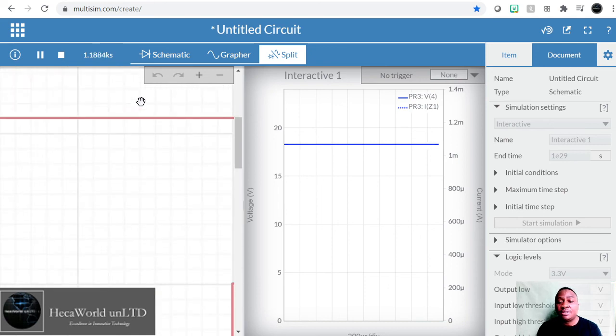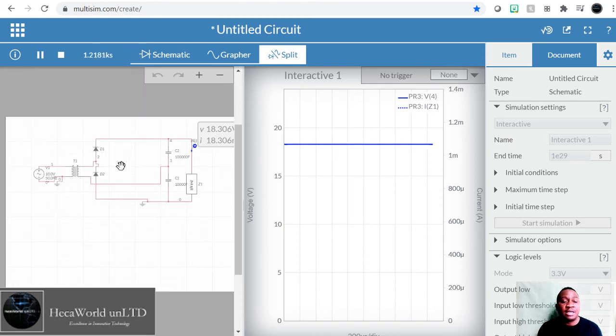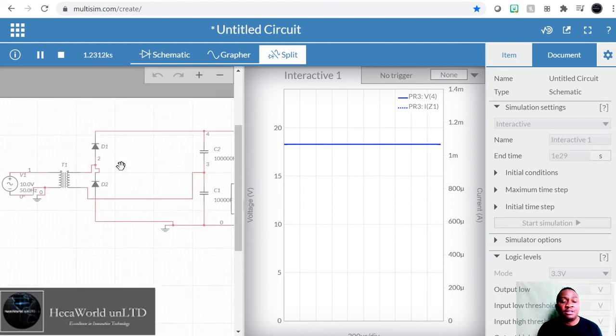All right. So if you do that correlation, I want you to internalize this formula. It's not really that complex, but I just want to make sure that it's communicated properly. So when you have C equal to Q over V, and Q is IT, the I and T are in the numerator of V. If V is constant, then to charge a higher C, you need more I and more T, or more current or more time or more of both, right?